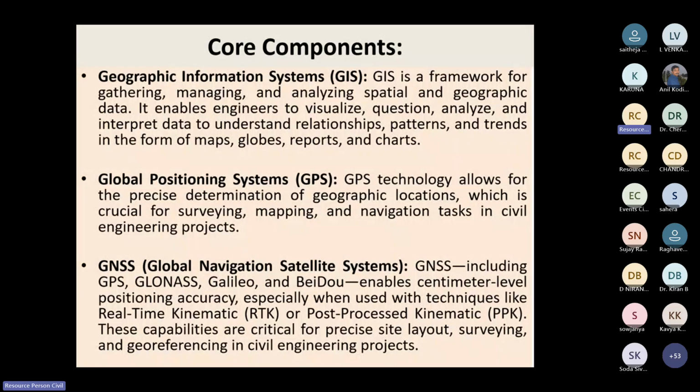GIS provides a lot with vector-related information. Remote sensing and photogrammetry are pictorial information. If you convert anything into vector form with GIS software, you get the feature information within KBs of data. Suppose one image contains 1000 MB, 100 MB, 50 MB, 75 MB. It may take a lot of space on our hard disk. But when you convert that into vector form in GIS, it takes very little space on the hard disk.